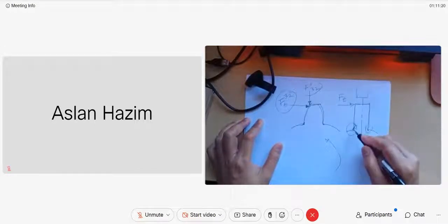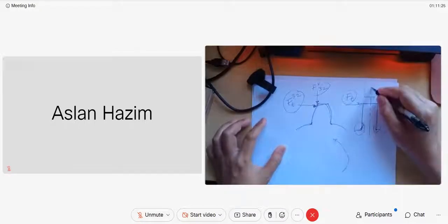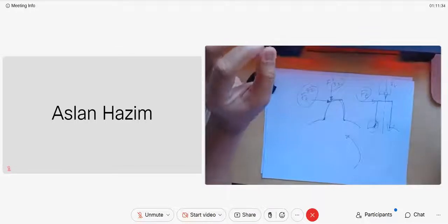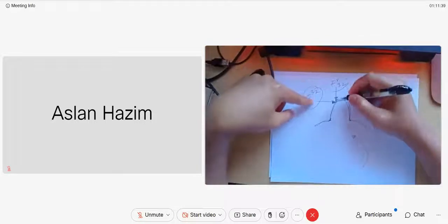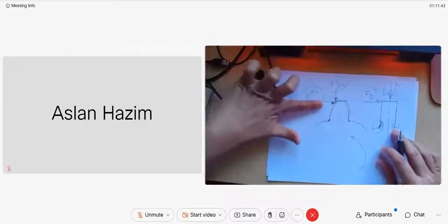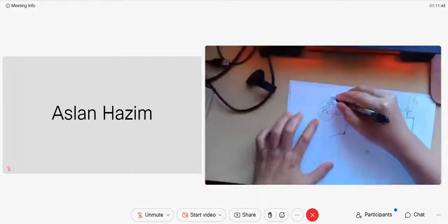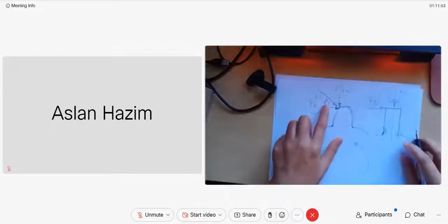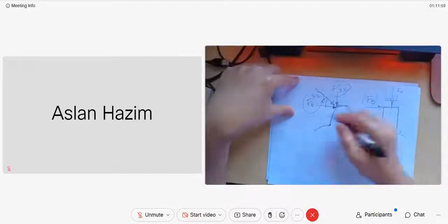So the sigma bending caused by the F tangent is what we have to calculate. We can ignore the F radius. Actually, we have F radius on gears, pointing to the center of your gear, but we can ignore it because it is actually harmless. It is small and will not harm the tooth. The one that is critical and will harm the strength of the tooth is your F tangent. Remember, in a gear we have a total force, and phi is your pressure angle. The pressure angle of your gear is 20 or 25 degrees.